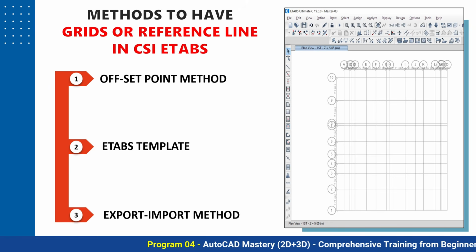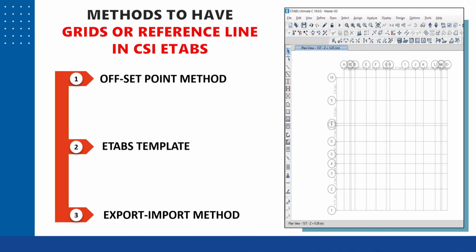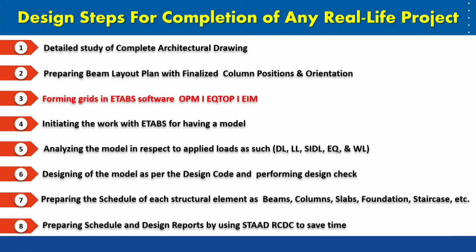And guys, when you are going to land in the Etabs software, the first thing needed is to have the grids in the Etabs software. Now there are different methods to create the grids in the Etabs software, or you can call them reference lines. If you are not going to prepare the reference line, the grid line, the center line, then it will be very difficult to do the correct modeling.